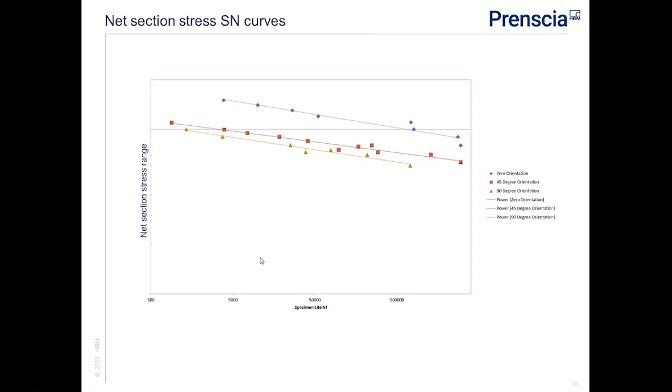So, for example, I think if we think that some damage parameter at the most critical location in the specimen is what's going to control its life, then we should use our FE to turn this conventional SN curve into curves that correlate life using the local value of the damage parameter calculated using the FE. So this is what we've started to do. And the easiest one to do, because it gives you a unique critical location in each specimen, is the strain energy density approach.